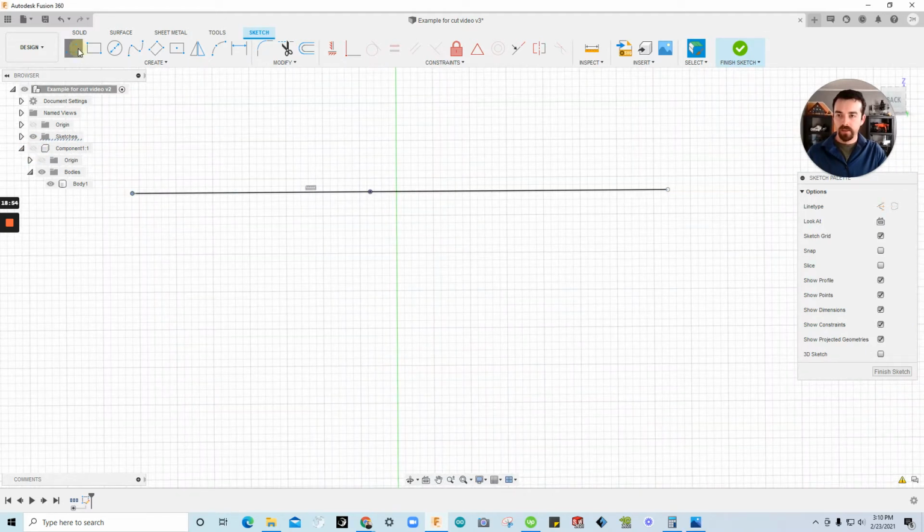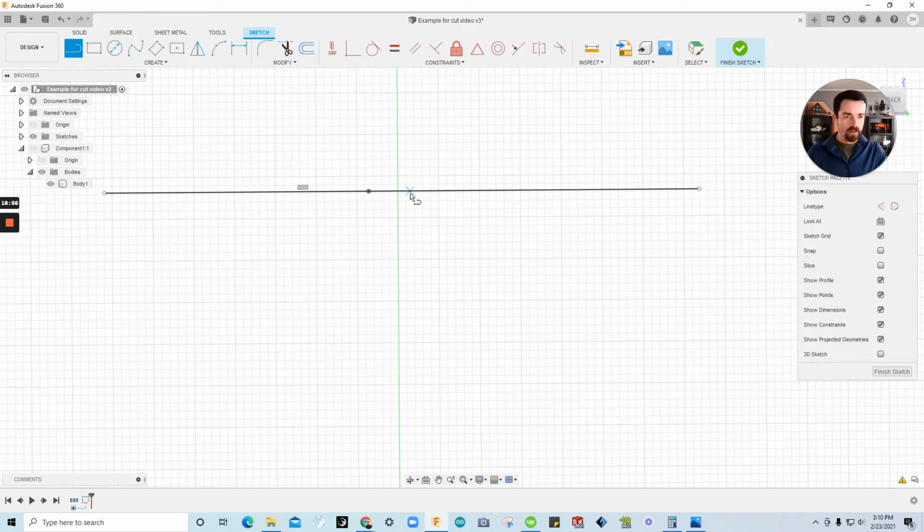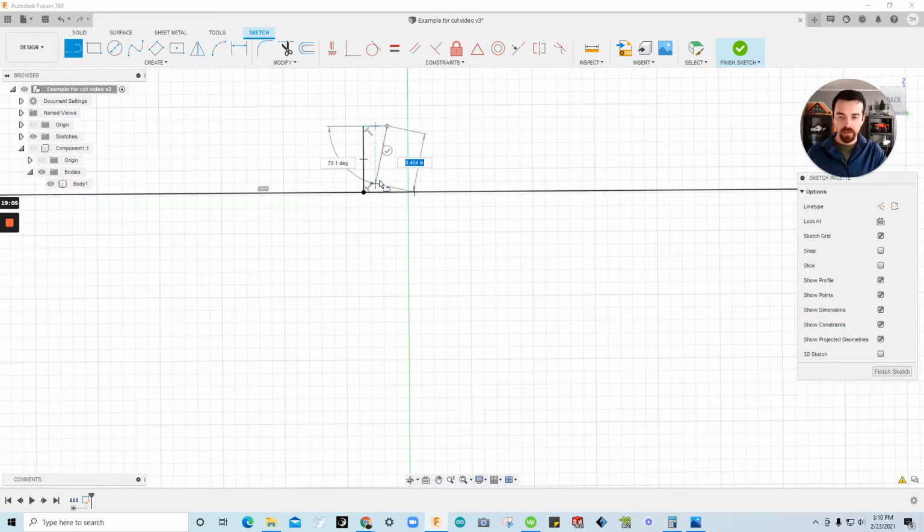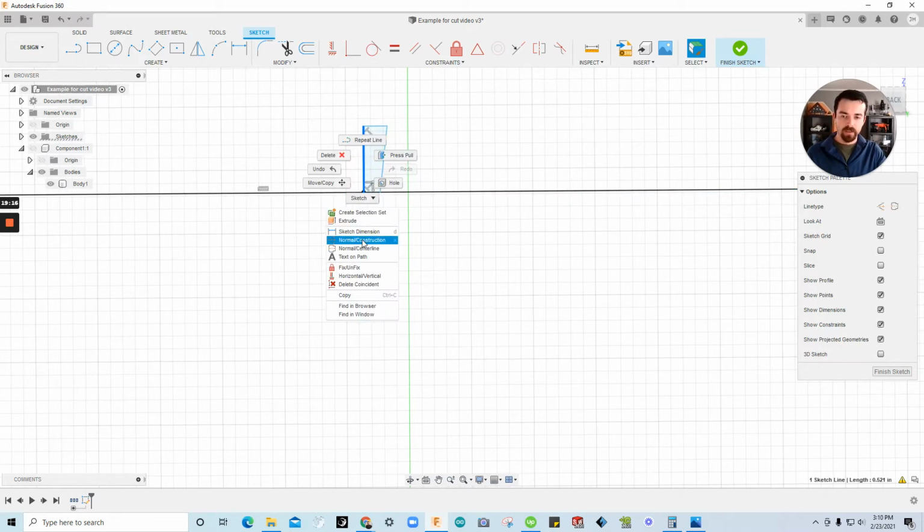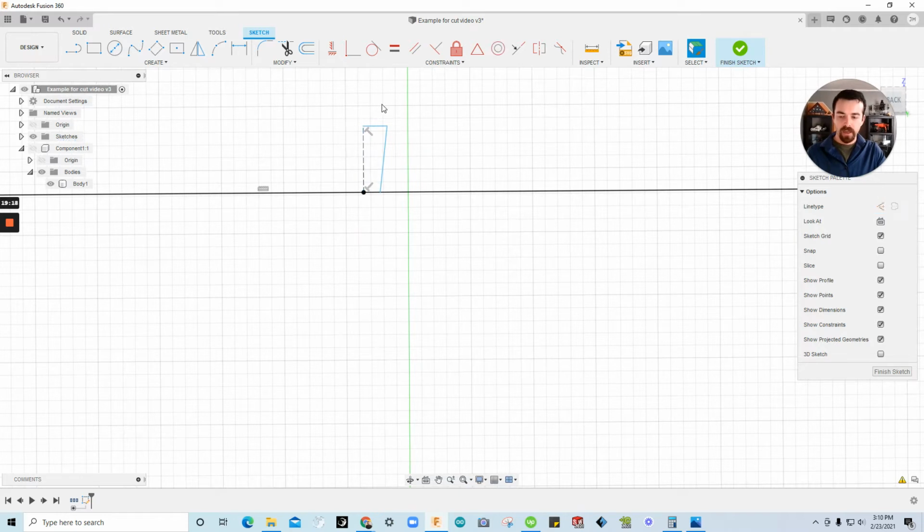Now let's draw out our dovetail. These don't matter too much visibly because you're going to hopefully cover them up once you've adhered your two parts together. I'm going to draw out this basic line. Careful not to use all those locks. Just let it be about like this. Draw that. Turn this line, click it, right click, turn it to construction. And then click D on your keyboard for dimension. Dimension can also be clicked here.